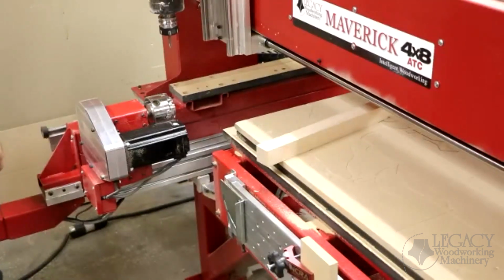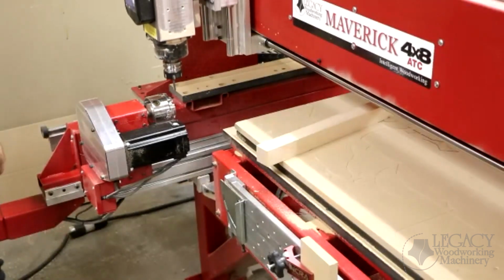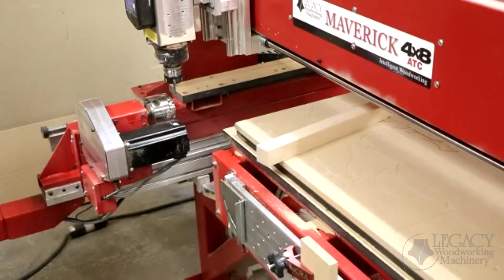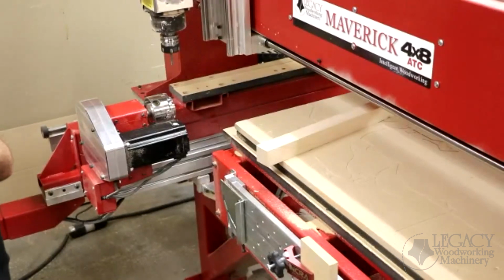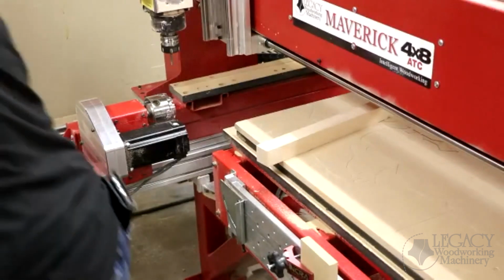If I lower this down, you can see we're 1 inch out in front of the part. So this, I set up 2 offsets. And that's how I drew it up, with X0 out 1 inch. So I created a brand new offset called the 4-jaw chuck with 1 inch, so I could use that. Right now, I'll raise this back up, step around and put the blank in, and then we'll start cutting the part.